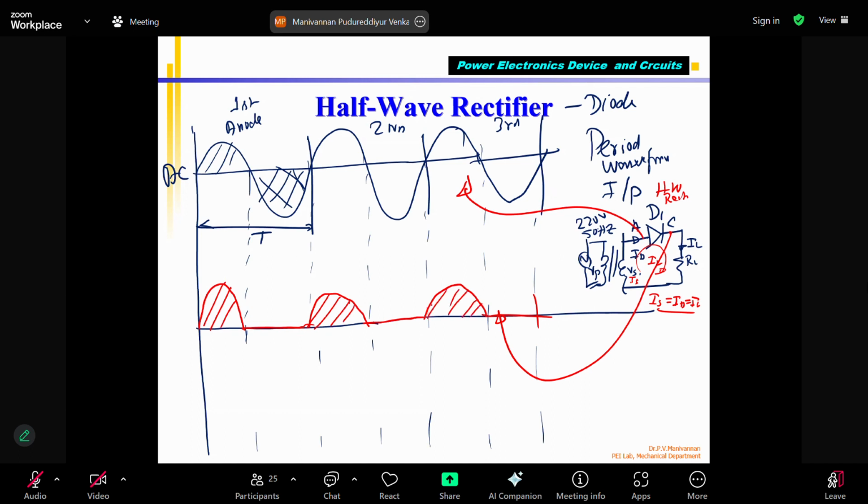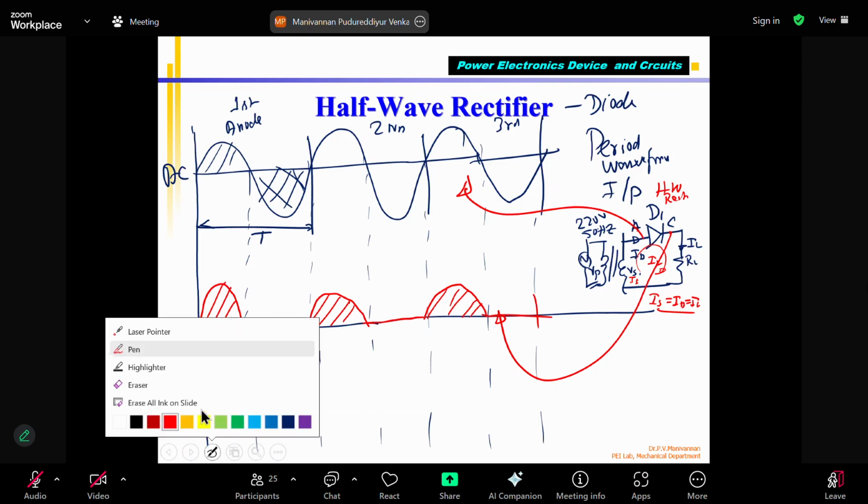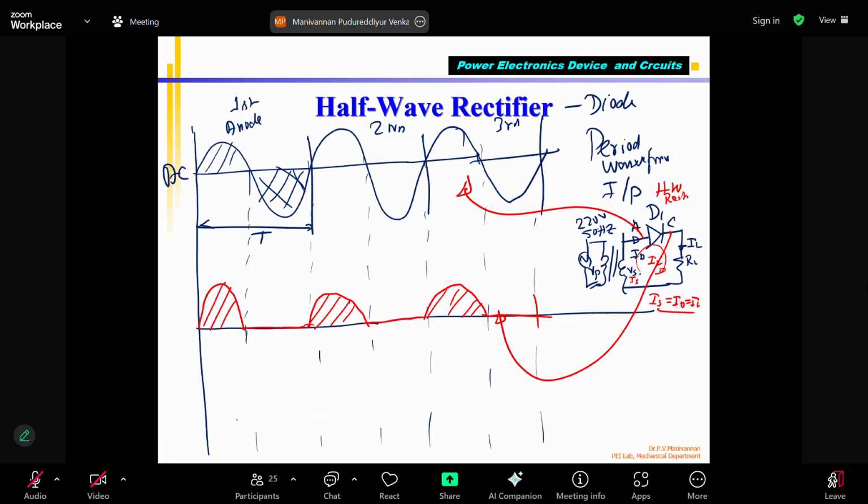There is a small mistake here in this second half-wave rectifier output. Can anybody with an electrical background say what it is? Suppose the voltage Vs equals 5 volts. I gave 220 volts, and it is a step-down transformer, so 220 volts is reduced to 5 volts. That means the secondary has fewer turns compared to the primary turns. So that is a step-down transformer.